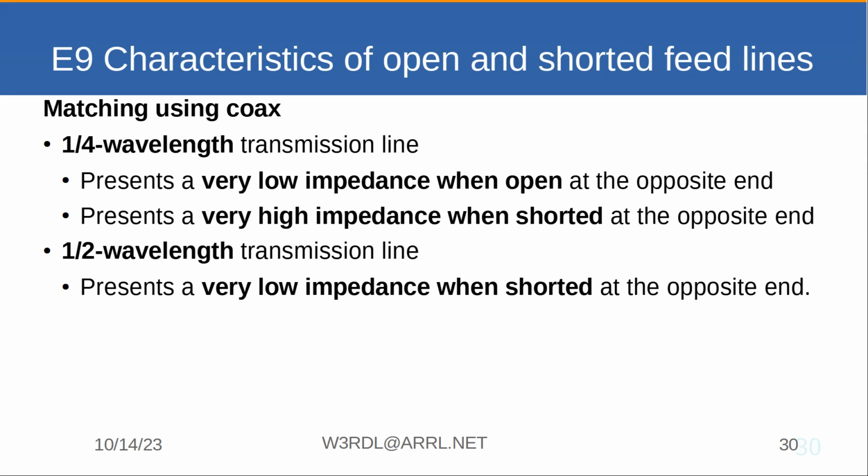It's either going to be at a peak or zero. Yes. If it's a multiple of a quarter wave, it's going to be high or low. And at even multiples, it's going to be the same. It's always going to be zero. Well, if you start off shorted, yes. If you start off open and it's a half wavelength long, it's going to look open.